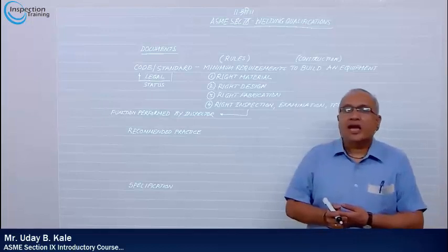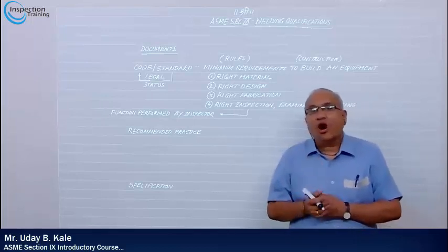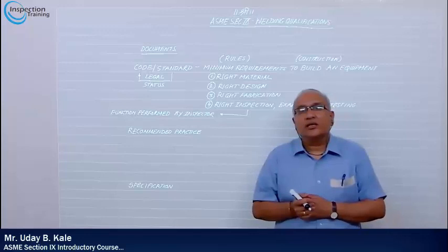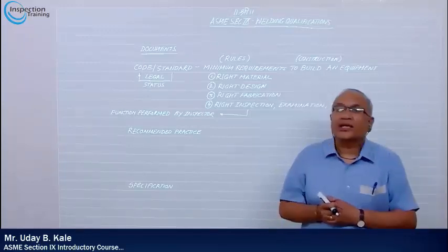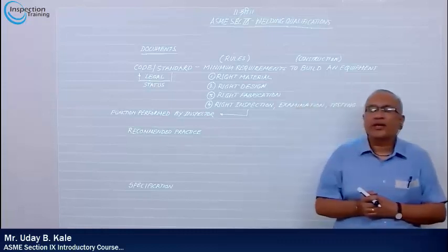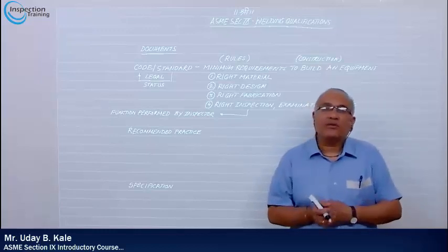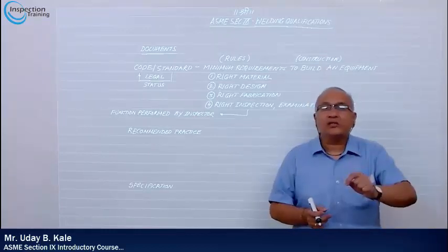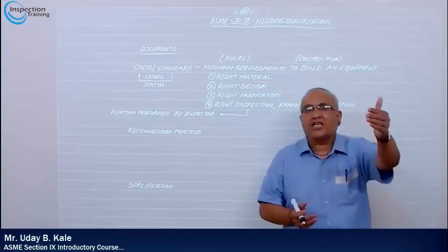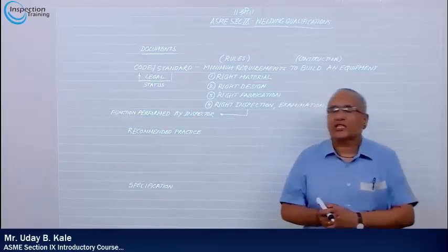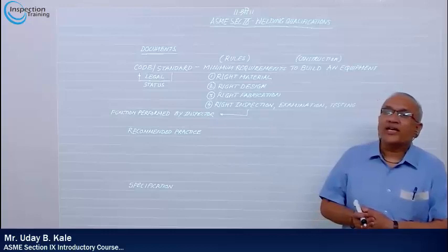Seeing and signing off all the documents before a hydrostatic test, which is typically a hold point, is a function of the inspector. So whatever the inspector does is inspection, as simple as that, as per the ITP, inspection and test plan, or quality assurance plan.